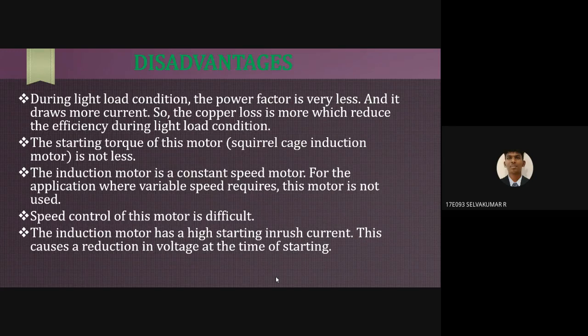During light load condition, the power factor is very low and it draws more current. So the copper loss is more, which reduces the efficiency during light load condition. These are the advantages and disadvantages of using three-phase induction motor.